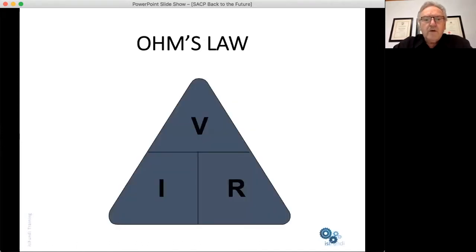You will recall that way back in the distant past when you did physics, you learned about a thing called Ohm's law. Well, Ohm's law is one of the electrical principles that we deal with in cathodic protection. It governs the relationship between voltage, current, and resistance. And in order to achieve the current that we need for cathodic protection, we are given the driving voltage by the voltage of the actual alloy. And therefore, the only thing we have left to play with is the resistance.